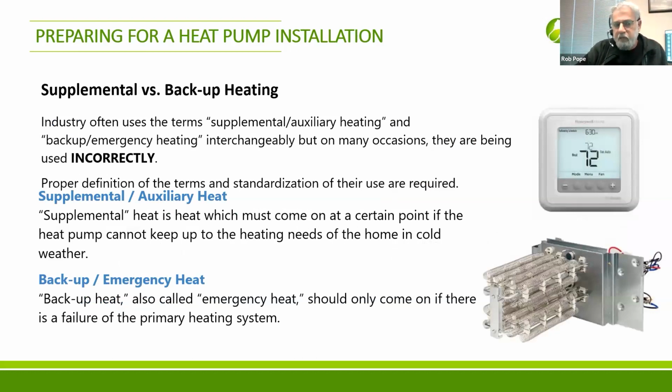Supplemental versus backup heating means this: if you have a heat pump sized to meet a percentage, like 80–90% of the load of your winter design condition, and there might be a week or two where it's not capable, you're going to need to supplement that or provide auxiliary heat. In other words, you're boosting that heat pump's capacity with another form of heat. Electric strip typically, right? That's supplemental and auxiliary heat.